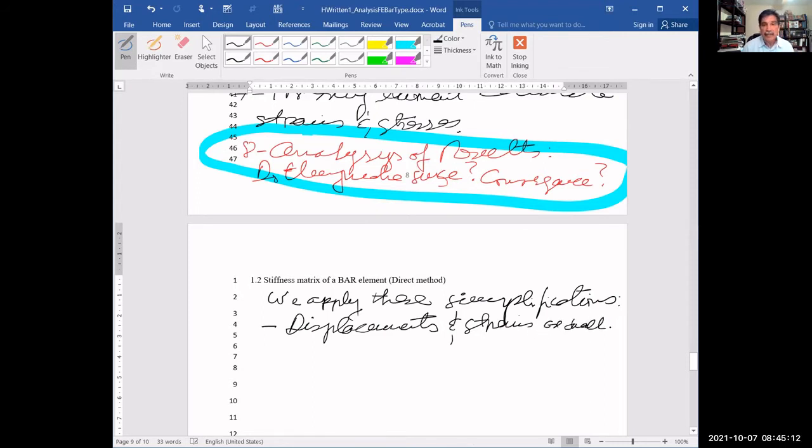So, for example, when you calculate the strain, you say delta L divided by L, right? If you have something that elongates, the normal strain is delta L over L. And you wonder, is the L the final or the original L? There's no difference because we're assuming that the displacements are small. So epsilon x is the elongation divided by L, and this is more or less equal to delta L divided by L, because the difference between the original and the final length is negligible. Why? Because we're assuming that displacements are small. It's typical of our analysis, okay?